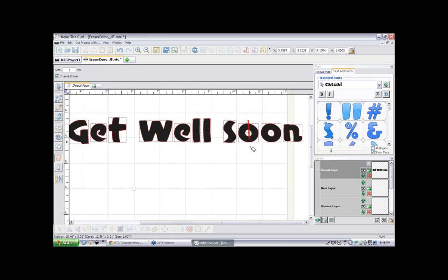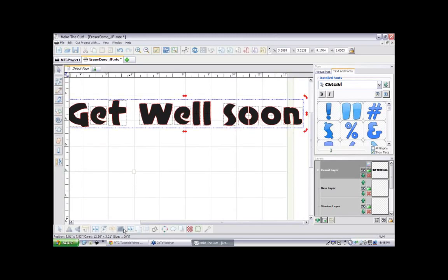So I click and drag, and I put my eraser right through the plus and release. Oh, but I forgot the inverse. So undo, you have to make sure it's not on inverse. Then you can click and drag, and that separates the pieces of the letter so you don't lose them on a stencil, but you still have to do a break. Well, I did a join. You have to do a split so the pieces will be separate.